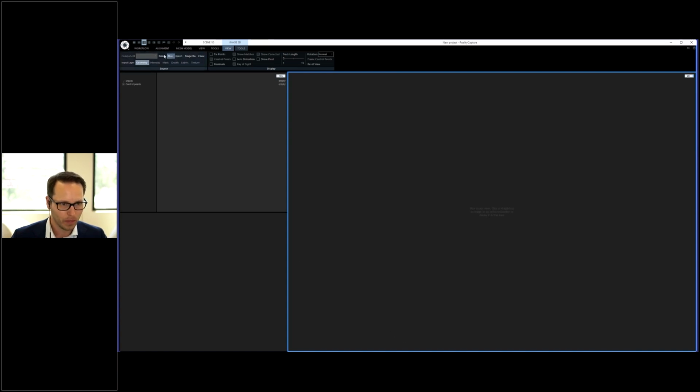So the first step is to get your images imported. We're going to start with our aerial images. Today we're going to do a demo of a building that we captured in Savannah about a month and a half ago. The reason we captured this structure was to do some deviation analysis, or plumbness analysis, more exactly, of all their facades. Combining terrestrial scanning with photogrammetry was a great example of how this process can help.